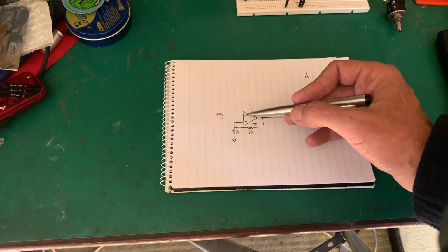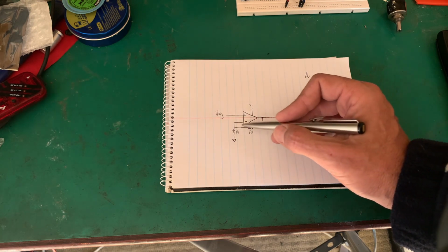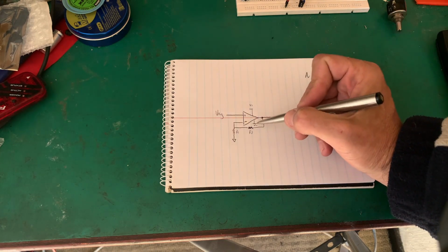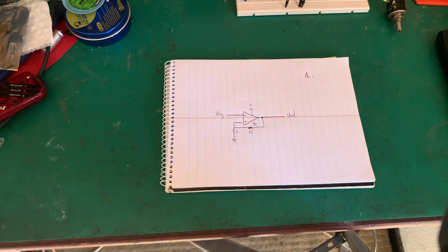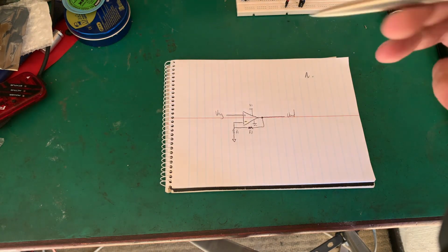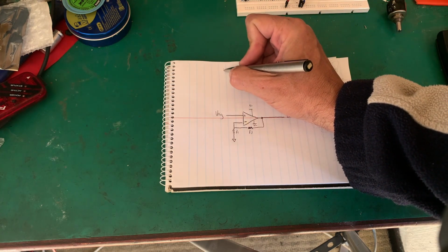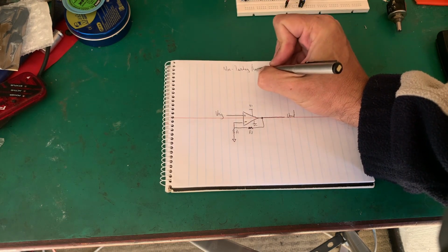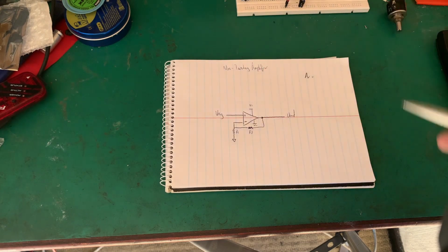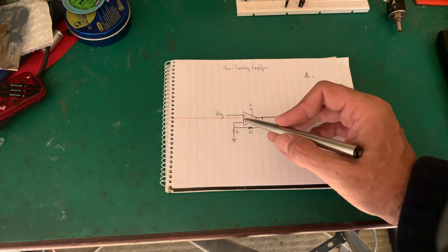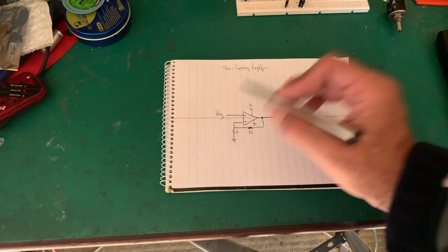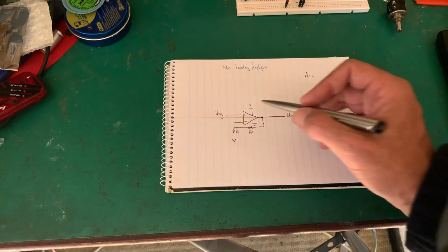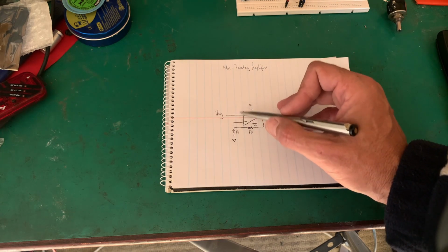Now we have our signal on the non-inverting input, and our feedback through the two resistor dividers is tied to ground. Aha! Well, first of all, we call this the non-inverting amplifier. What it means is the output will be in phase with the input, and we can see that. The signal goes up, this signal will go up. Why? The op-amp will do whatever it can to make those two meet.